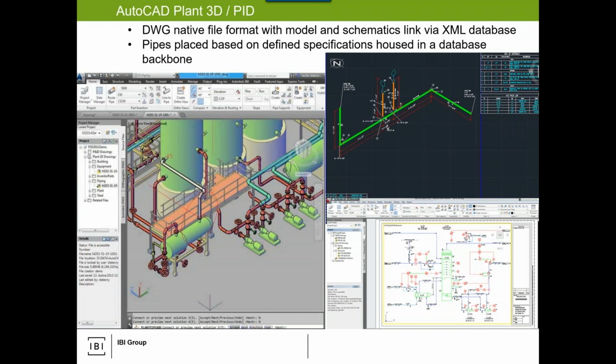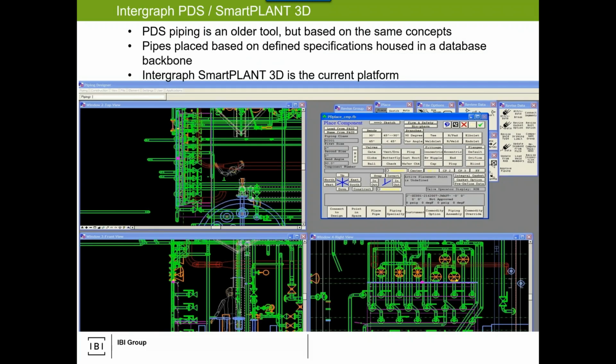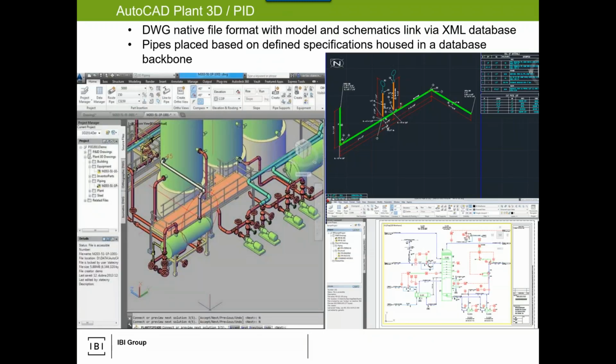And this is quite a good tool. Their spec catalogs are quite robust. They have a lot of the components that you need. It's very comparable and compatible to the others. Again, ISO 15926 compatible. So you're selecting items, you have your bill of materials. This here in the top left, I wanted to just talk about this for a moment.